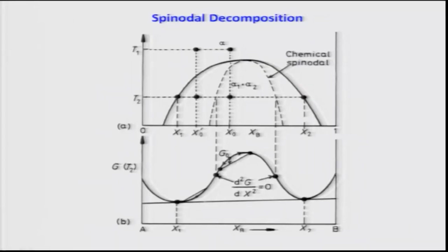Now here the phase diagram is shown at the top. Okay, so let us first look at the solid line of the phase diagram. Because of the presence of this kind of hump in the free energy composition diagram, you can see that it shows a dome shaped structure. It just goes up and then goes down. It is a dome shaped structure. Now such a phase diagram is a signature of what is known as spinodal decomposition. Let us explain in detail what actually happens. Given that you know the phase diagram exists, I am only asking you to concentrate on the solid line. Do not look into other parts now, which will be coming slowly.